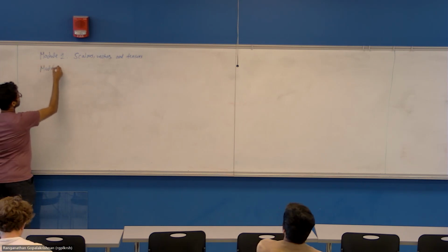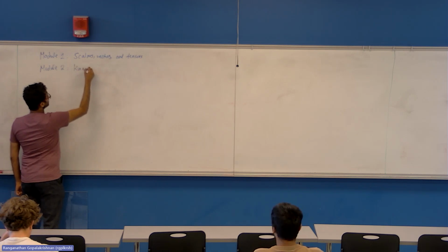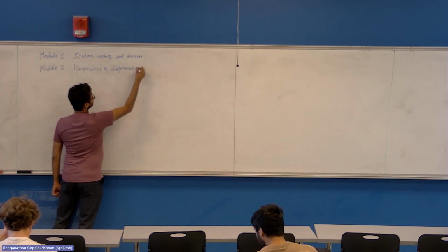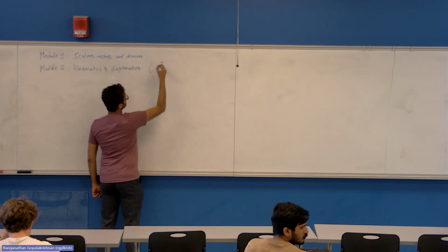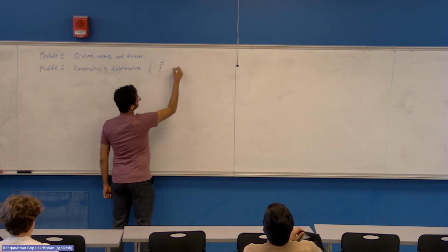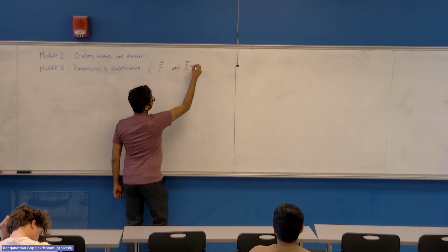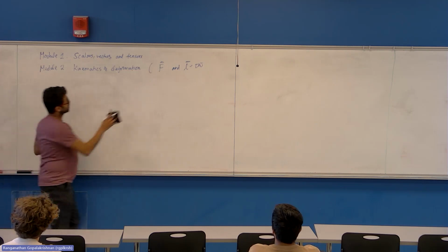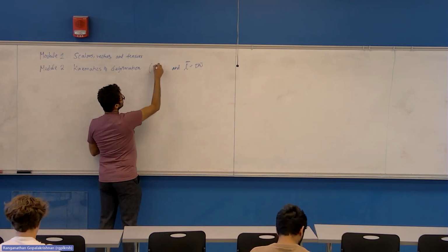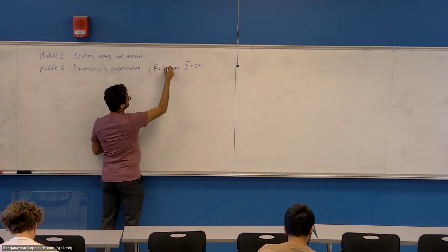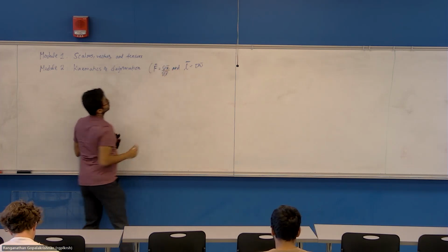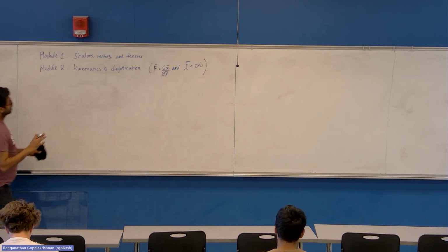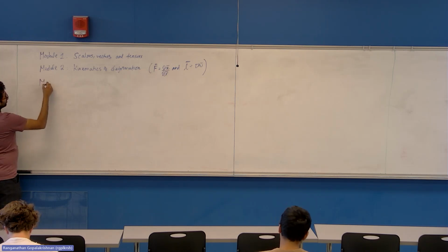Module 2 has been to analyze the kinematics of deformation, wherein we saw two main concepts, the deformation gradient or the deformation tensor, as well as the velocity gradient L, which is a spatial tensor, second order spatial tensor, and the deformation tensor F or deformation gradient is partial x over partial material X. So these are the two core concepts, and around that we saw many other ideas that I'm not going to elaborate further. And then we are now starting module 3,